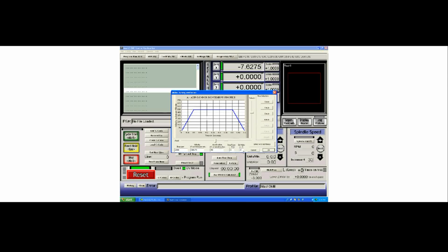The only time you'll change a direction pulse width is if you find that you're losing one step each time you change direction. For 99% of users, you will never change this above 0. For 90% of users, you will never increase the step pulse above 0. Some controllers, however, do require up to 5 microseconds of additional step pulse width because the optocouplers in the drivers are a little slow, and this gives those optocouplers a longer time to adjust.